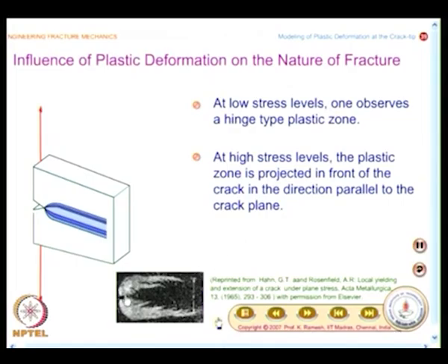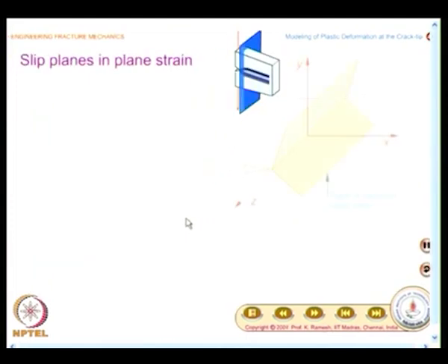The mechanisms of identifying the maximum shear stress differs in this place as well as at a distance away from it. So, we will pass a plane close to the crack tip and look at what is the kind of idealizations that we are making.